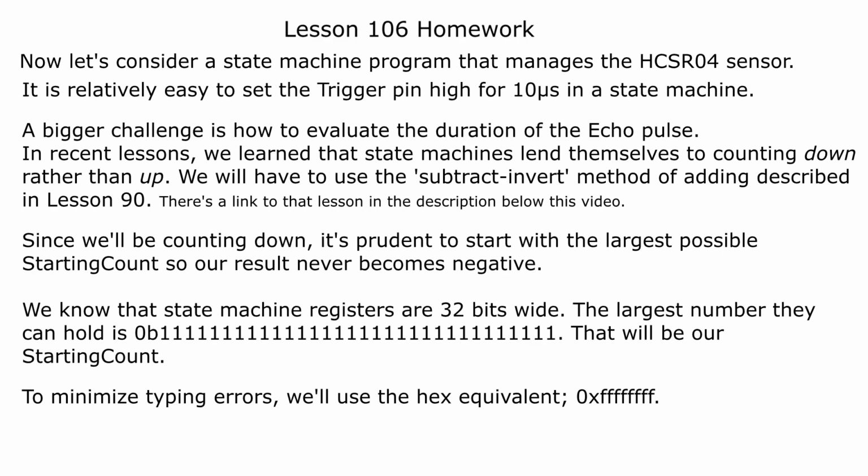It is relatively easy to set the trigger pin high for 10 microseconds in a state machine. A bigger challenge is how to evaluate the duration of the echo pulse. In recent lessons, we learned that state machines lend themselves to counting down rather than up. We will have to use the subtract-invert method of adding described in Lesson 90. There's a link to that lesson in the description below this video.